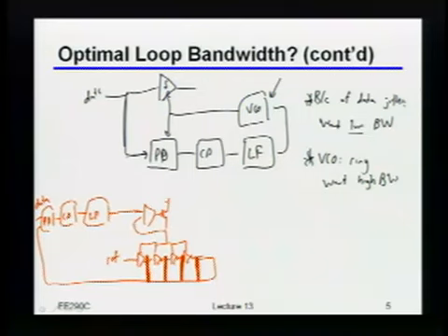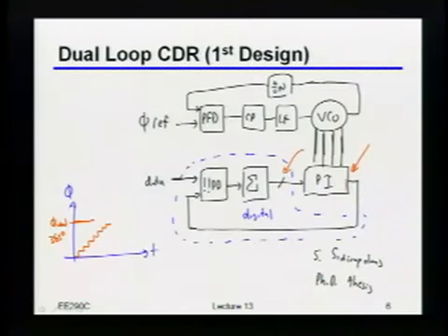But remember, let's say that I'm doing, I don't know, a 5 gigabit per second link or something like that, or maybe even a 10 gigabit per second link. A typical number for timing resolution that you'd like to have is on the order of 2 picoseconds or so. By the way, there are ways you could get 2 picoseconds from an inverter, but trust me, it's painful. And as you'll see a little bit later on, the way we build these, it's actually fairly straightforward, or at least, it really doesn't cost you too much power to actually get that kind of resolution. That's a great question, though.